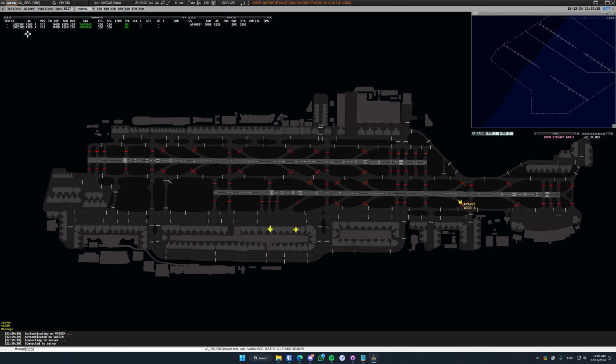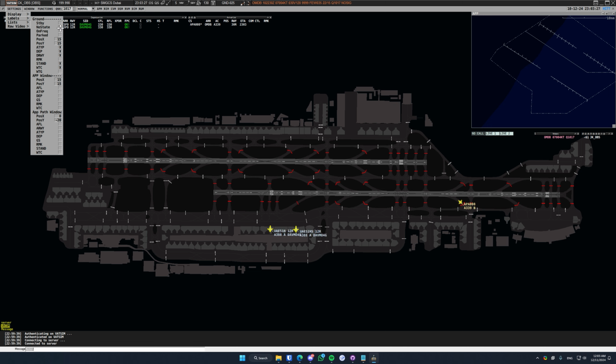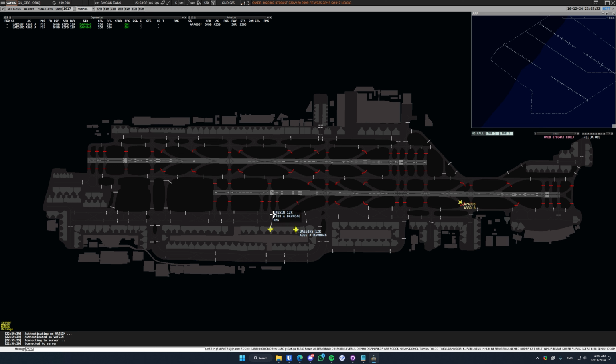The first setting you're going to change is on this bar here in the settings window. Go to labels and untick no state. You'll see that by doing this, we're now able to see the tag of the aircraft on the ground. We're able to see the call sign, the assigned runway, the aircraft type, aircraft category under Enhanced Wing Turbulence Separation Minima, which is an improved and revised version of the standard ICAO separation or aircraft categories, the standard instrument departure, and any remarks left by a controller.